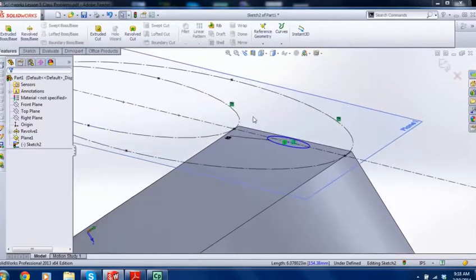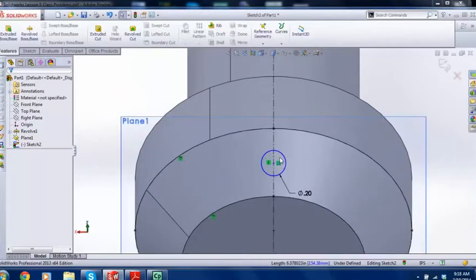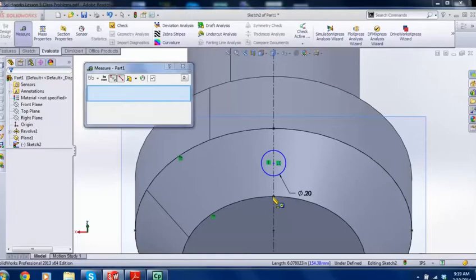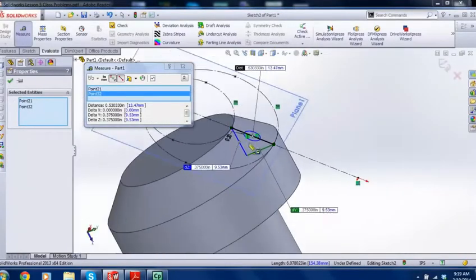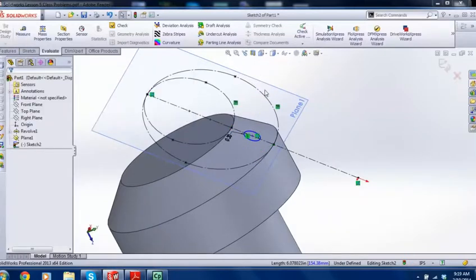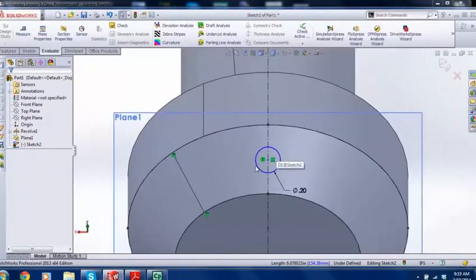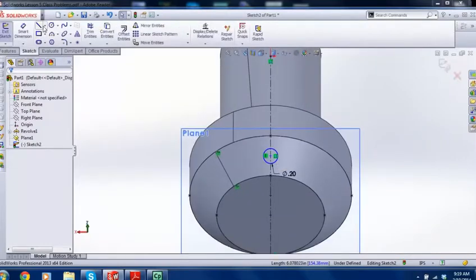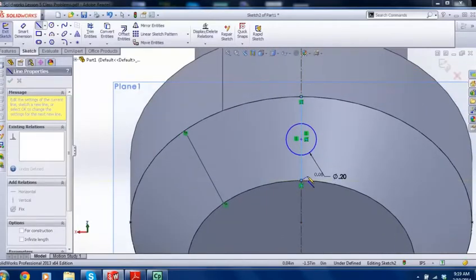All of this work that I'm going to is to ensure that this hole is centered on that face. Now, let's do this. Let's measure this from that point there to that point there, and let's look at it. Okay? The distance is 0.53 of an inch. So, I'm just going to put a dimension. There's probably an easier way. Yeah, I'm making this hard. Watch this. Let's just put a line in from that point to that point.